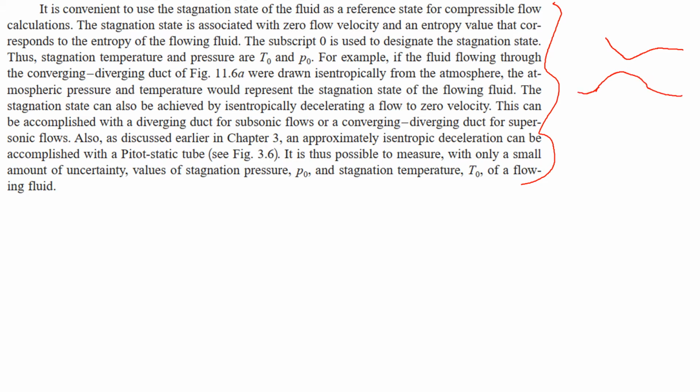Let's say if this is our converging diverging duct, and we are interested in finding pressure, temperature, density inside this converging diverging duct, because inside there are compressible effects, and we are dealing with compressible flows now. So to see the properties like pressure, temperature and density of a compressible flow, an ideal way to visualize it is in a converging diverging duct.